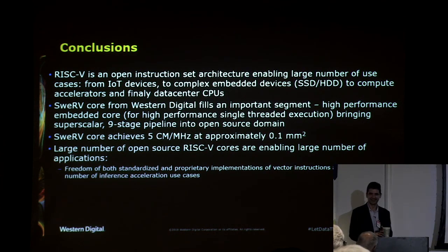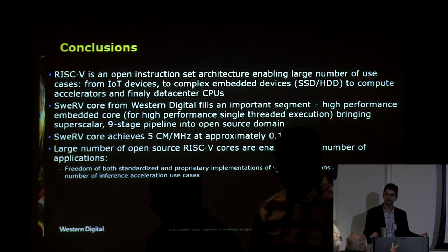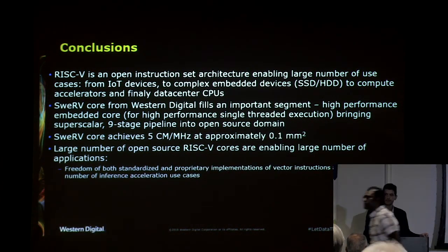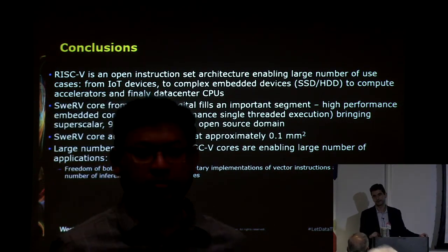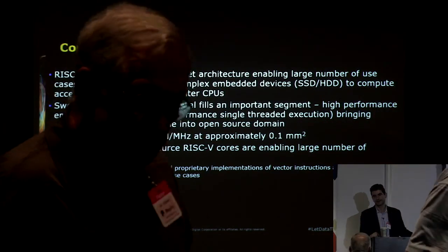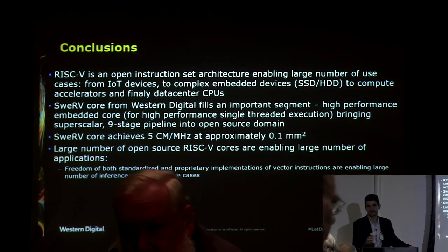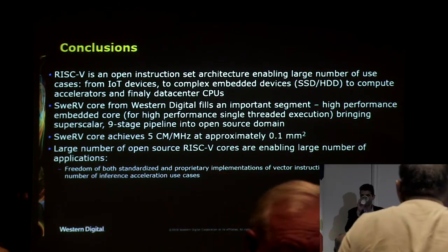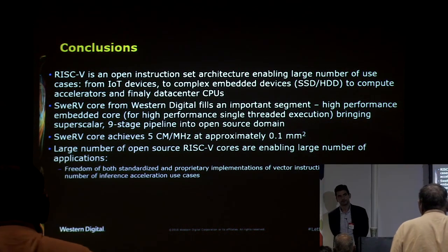Go ahead. Could you talk about IDEs and JTAG style debugging for Cortex-M4 level cores that would be coming out, which would be mainly used in smart sensing? Because right now in the ARM ecosystem, there's a large fragmentation between multiple vendors and ST-Link versus OpenOCD, PyOCD. And to me, hardware is great, but software makes it happen. And if there is no good support for that in RISC-V, then that's a problem.